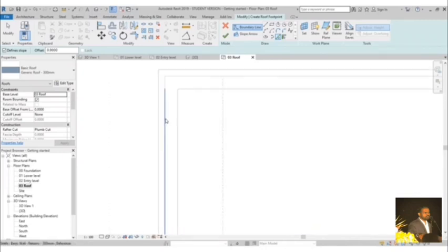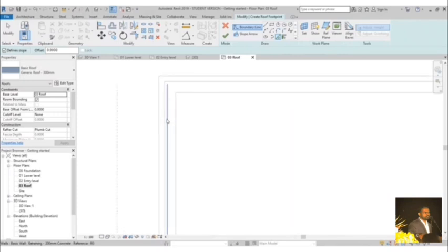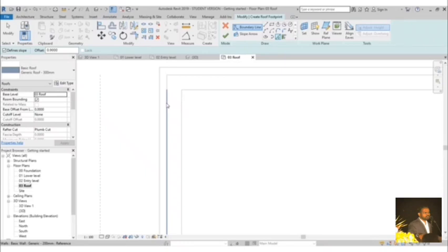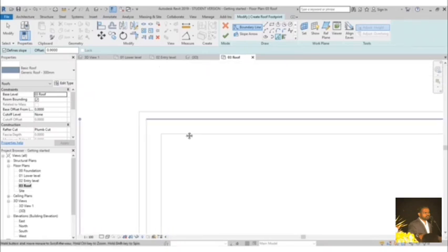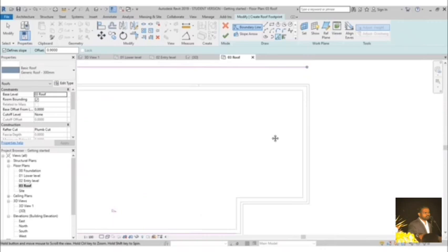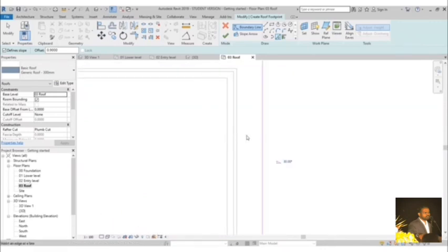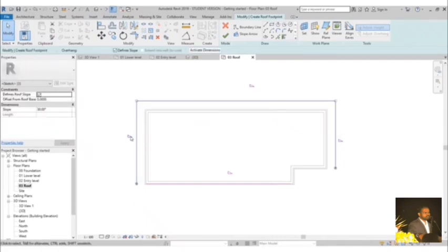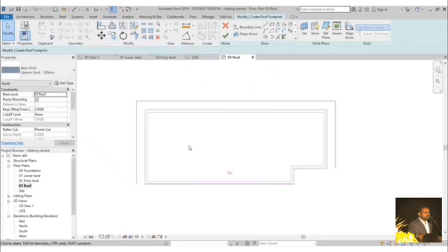Okay, so just zoom in and you find that location, and as you can see now it's on the wrong side. So let's see. You just need to approach it from the different side, and now you can click, same thing over here, click, and same thing over here, click. Now as you can see, this also has these sloped little symbols, and we actually don't want to have those slope symbols. These three edges actually don't have slope, so we just select them and uncheck here the finished slope. And just to connect it all, you can use the tool trim and extend.